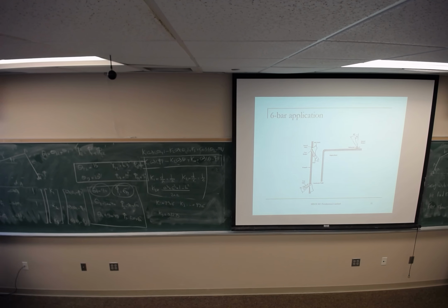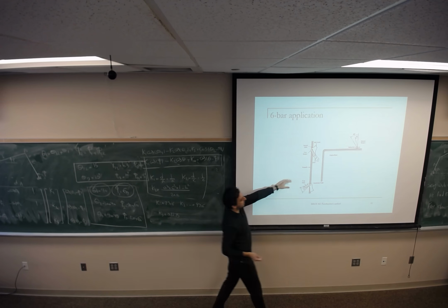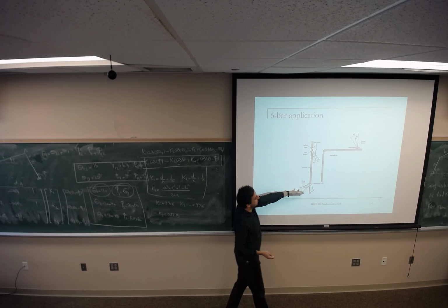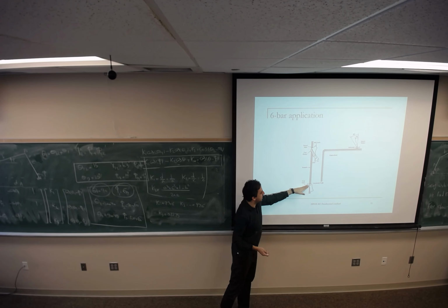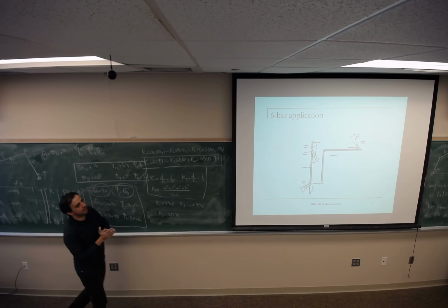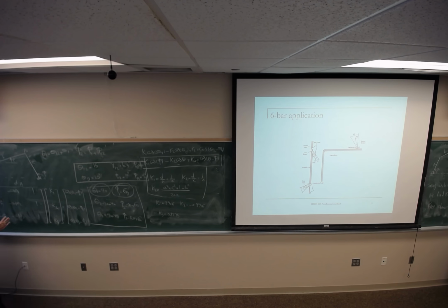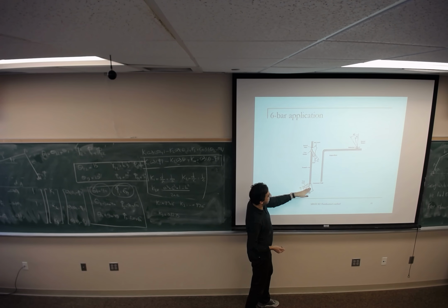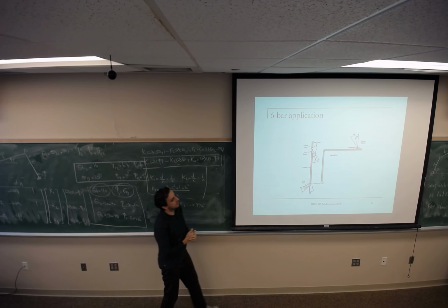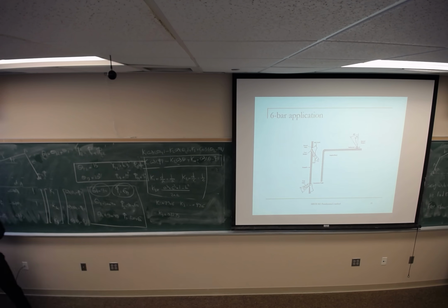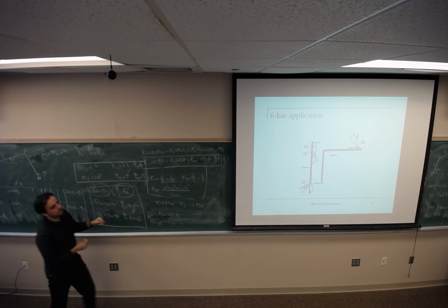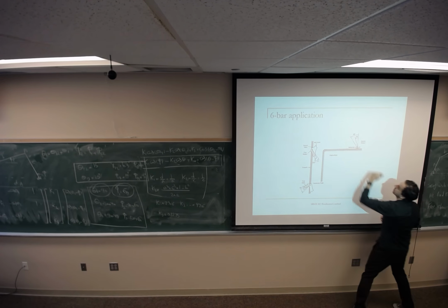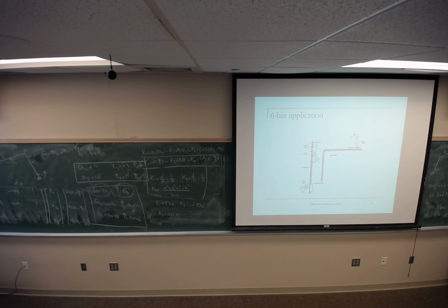So if any group is interested, we can talk about the angles, but if you pick that one, you should put some pointer so that I can make sure that it generates the desired function. Because just think, how can I make sure that by pushing this by 15 degrees, the middle crank is rotating by 10.5 and the carburetor is opening by 20 degrees? Somehow you should add some pointer to the mechanism which shows the motion of the mechanism.